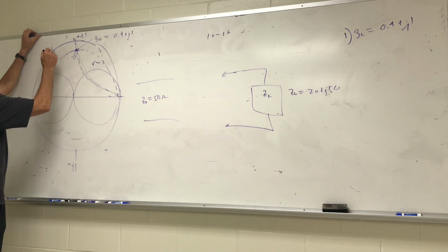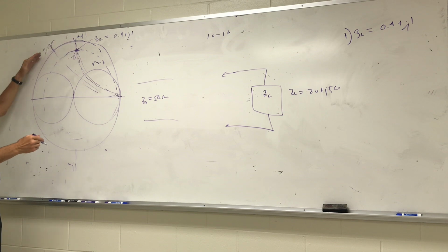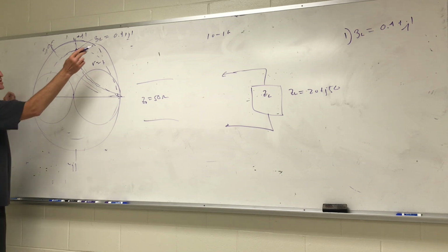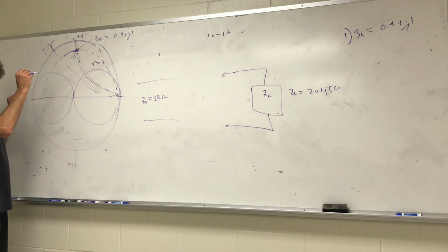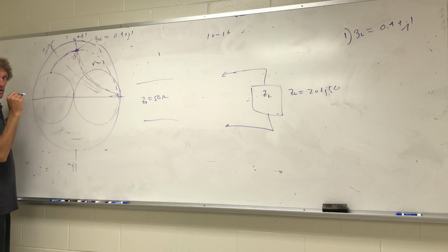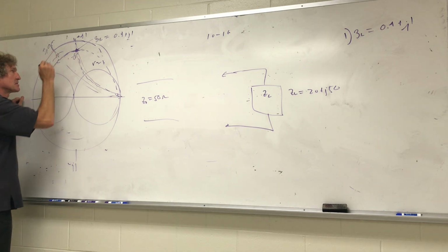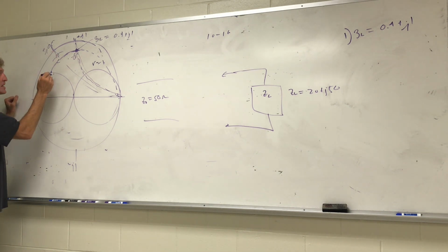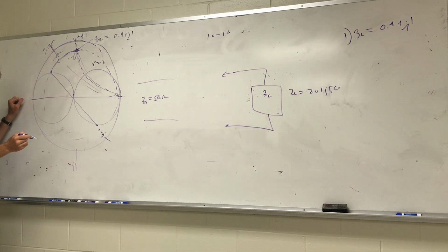Out here you're going to see values like plus J0.5, and this is an exaggeration, but you get the idea, the J numbers decrease this way and go to 0. So if we're at plus J1, we need a minus J, which would be a capacitor in series, until you got here. This is one possible path. Now we're here, we go to this circle, and I have 1 minus J something, correct?